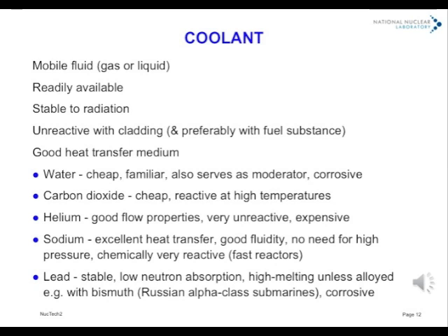Molten sodium provides excellent heat transfer, has flow properties similar to water, does not need to be pressurized to prevent boiling, but is very reactive chemically, especially with water, and is used only in fast reactors. Molten lead is stable with low absorption, but corrosive towards steel. It is also rather inconveniently high melting, unless alloyed with bismuth, which raises issues of activation.